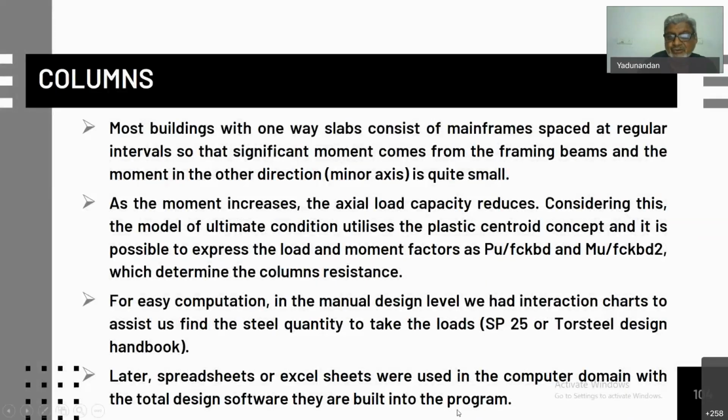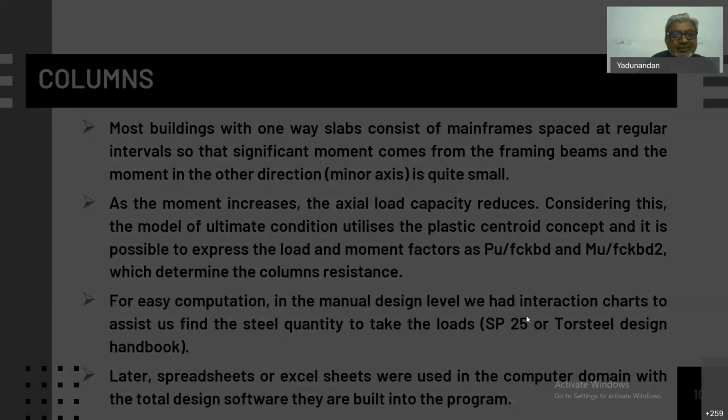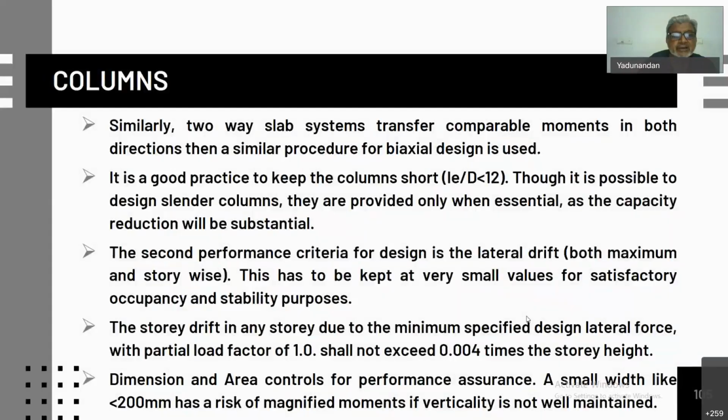square, which are the two controlling factors on which the column strength and tension are dependent. So these charts use these basic parameters of axial load and moment, and you use the column interaction charts, or you can develop your own spreadsheets and calculate the strength of the column.